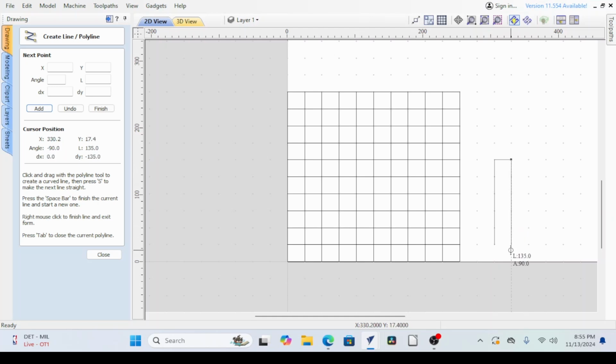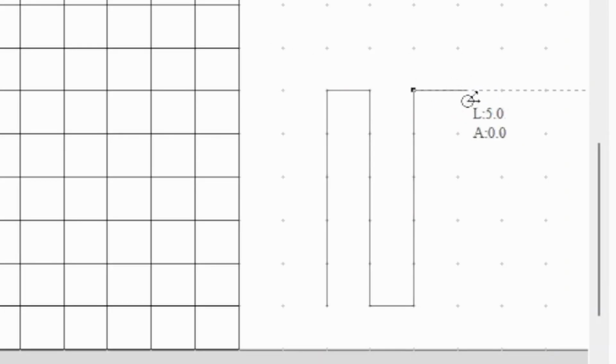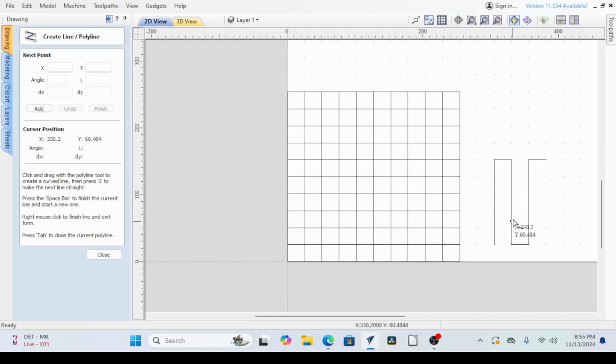And you were doing one of these polylines, and you end up with a scenario where you want to end it somewhere else besides that starting point. You can do that by hitting the space button of your keyboard, and that will terminate a polyline. Another thing that happens is, say you came over here and you ended it prematurely, then you can just create another polyline and finish out your structure. So hope that helps. I'm going to get out of here.